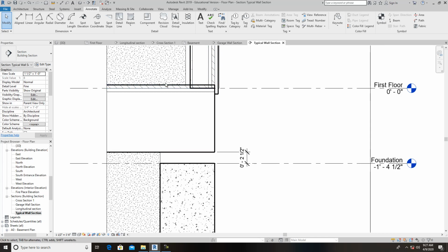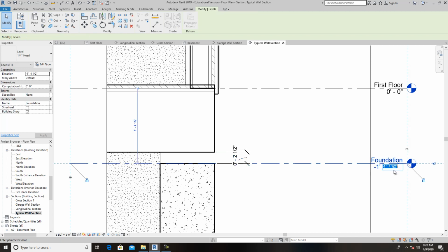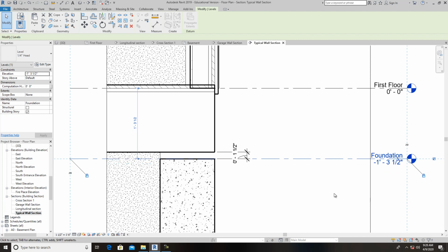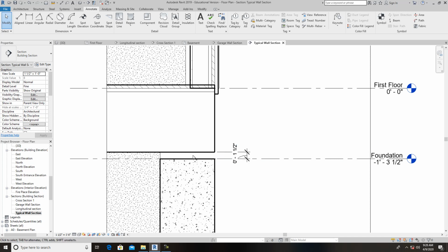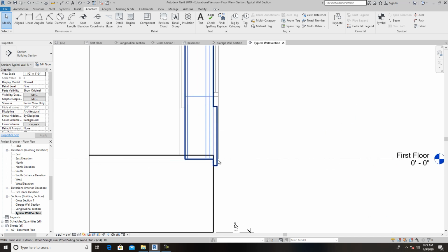You're not going to put your wall studs on top of your hardwood oak floor. You can follow the book, that's fine, I won't knock any points, but what I want you to do is this distance here should be 1.5. We're going to move this thing up 3 right there, and that's exactly what I want. A 1.5 inch gap right there. It's perfect.